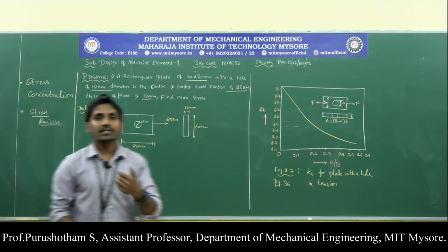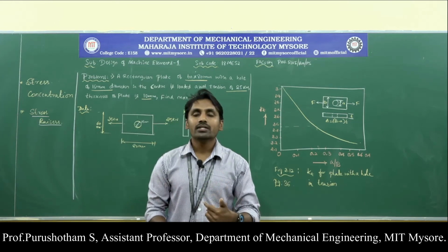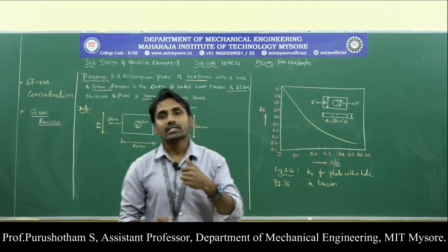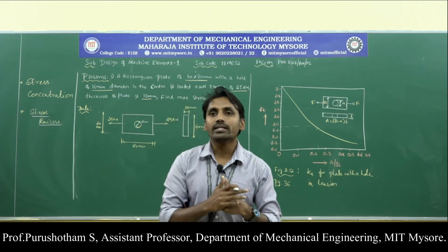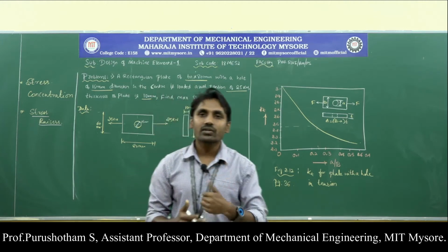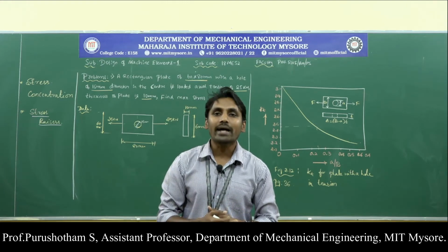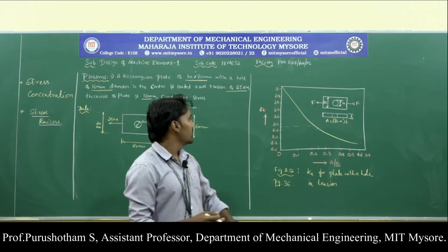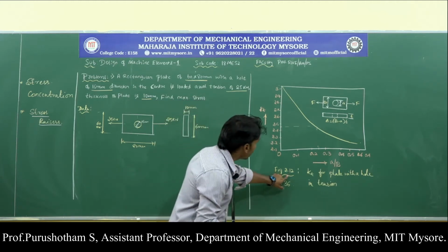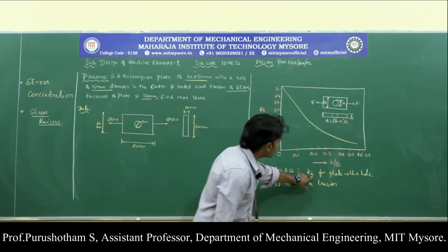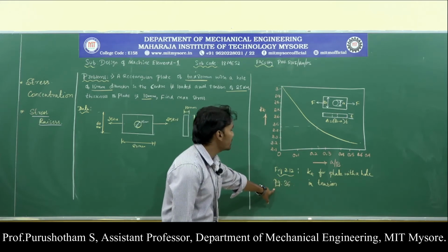To calculate the stress concentration factors, the data handbook has several figures, so we need to identify the figure which has the similar, exact case. By doing this we can calculate the stress concentration factor, and in terms of that we can calculate the maximum stress induced in the material. So for this, if you look in the data handbook, it is figure 2.12, that is stress concentration factor for plate with a hole in tension, which is present at page number 36.